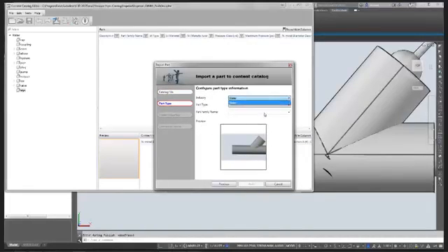Industry, I have water as of now. Part type, what do I want it to be? I cannot change, I cannot add to these. It's a Y, but I do have the ability to add a family name to it, Y, or maybe 350 PSI versus 250 PSI. This is your gate valve 250 psi versus gate valve 350 psi, or this is your ductile iron pipe versus PVC pipe. Your family is PVC versus ductile iron.